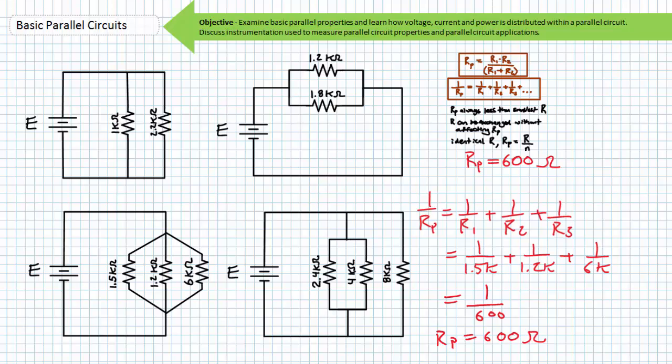Additionally, we can exchange the order of resistors in a parallel combination without affecting total resistance. We can make use of an identical resistor shortcut. We can, if we're unusually hard-headed, use the sum of conductances formula to solve for the resistance of a parallel combination of resistors in one mouse calculation event. And finally, and most importantly, regardless of the formula used, the sequence of engagement, the shortcuts applied, or your age, gender, race, class, or sexual orientation, you get the same answer, and it should be correct.